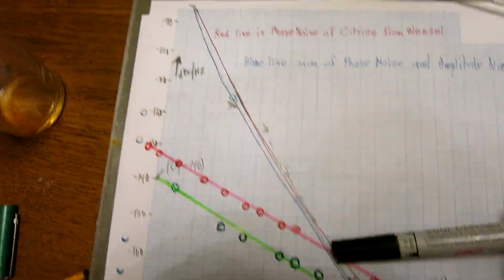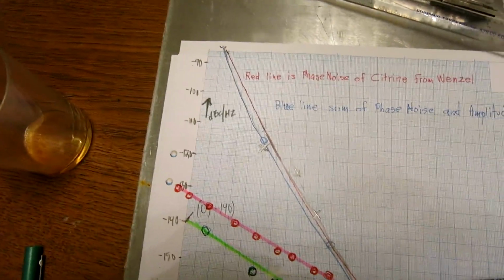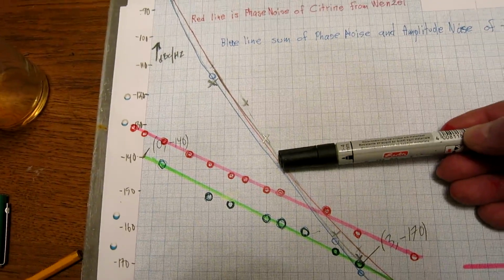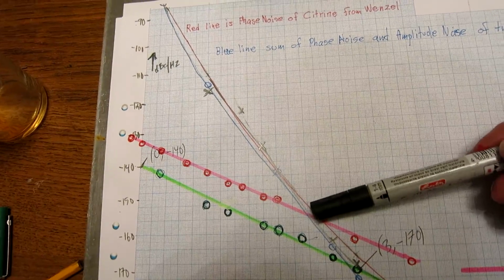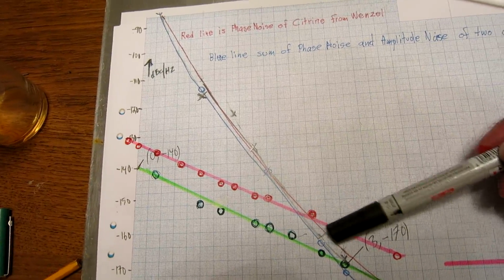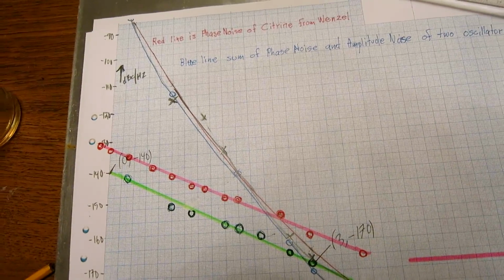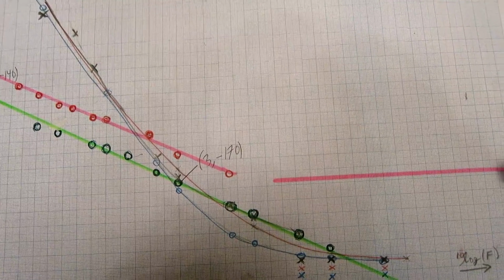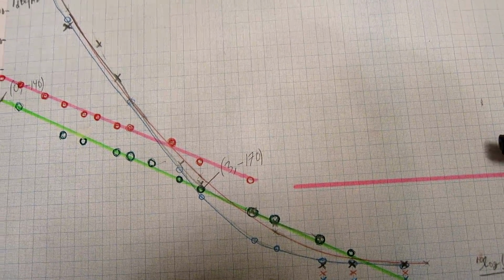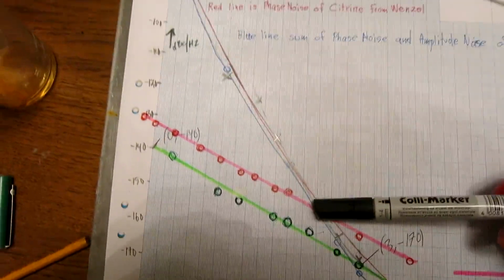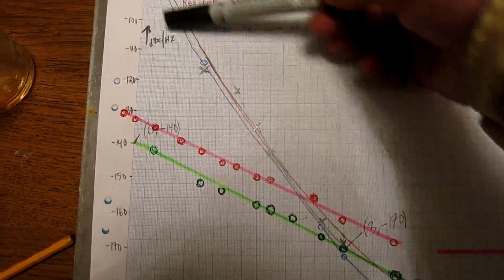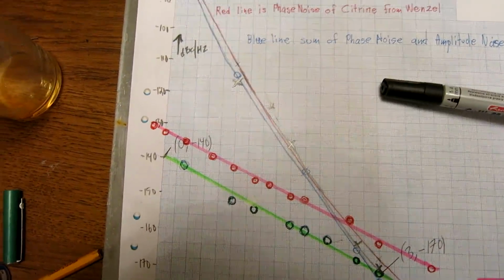and we can see at frequencies above, say, 100 Hertz, there is noise added by the amplifier, but not much flicker noise, because this flat noise figure comes from the device not being able to handle enough power. But below 100 Hertz, the noise from the oscillators dominates very much.